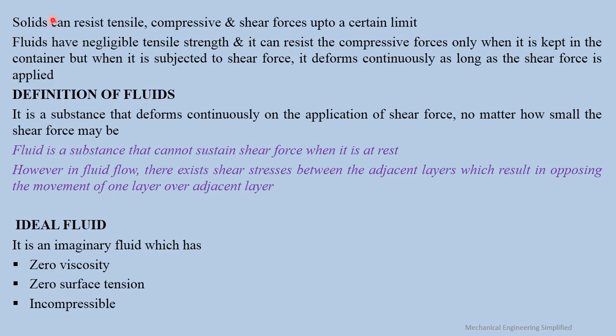Then, solids can resist tensile, compressive and shear forces up to a certain limit. And what is that certain limit? It is the elastic limit. Fluids have negligible tensile strength, which means fluid cannot resist tensile force. It can resist compressive forces only when it is kept in a container. But when it is subjected to shear force, what happens? It deforms continuously as long as the shear force is applied.